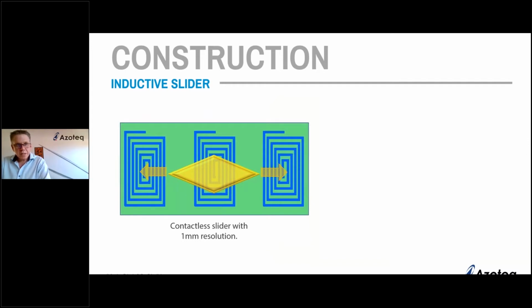You need to place coils, and the amount of coils and the size of the coils will depend on how much precision and how much resolution you require. But typically, you will design the coils underneath the travel direction of a metal target. So again, making this waterproof is very easy because the moving part can move in a slot that is on the opposite side of a sealed housing with the electronics all inside, sealed inside.